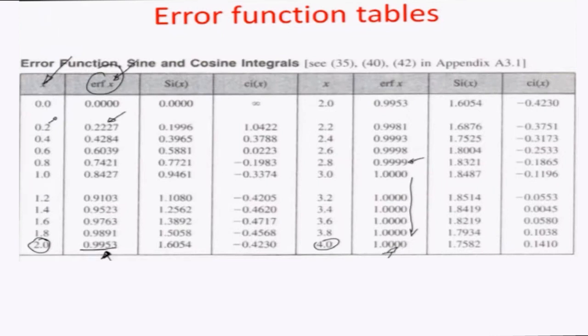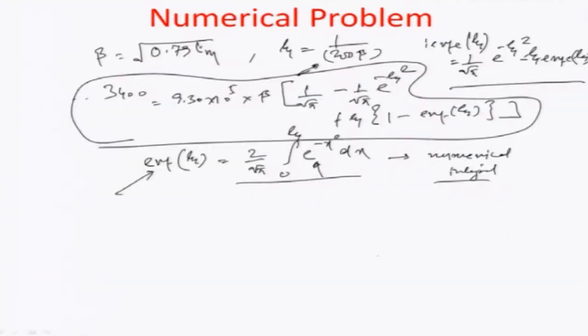So in this way, we can actually try to estimate by using a software the various values of zeta equal to 1 by 200 beta by plugging the beta value and trying to see what the error function comes out to be equal to. Plug this back here and numerically try to determine what beta can be.